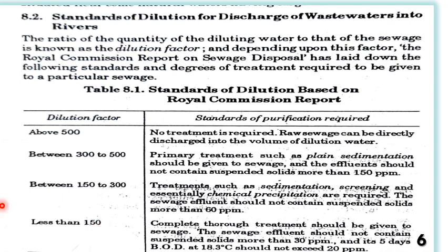Dilution factor. Because the river cannot flow throughout the 365 days of the year. Remember it. It flows fully only in the rainy season. In summer, the water will reduce and the flow will reduce. You see the condition of the flow, and then only decide how to dispose. The quality of sewage should be fit for the disposal condition. This is called dilution, dilution of sewage by using river water. Okay, that is how it is possible.